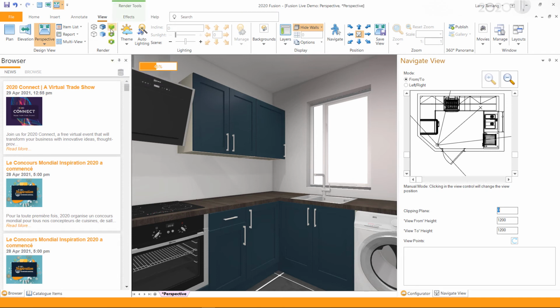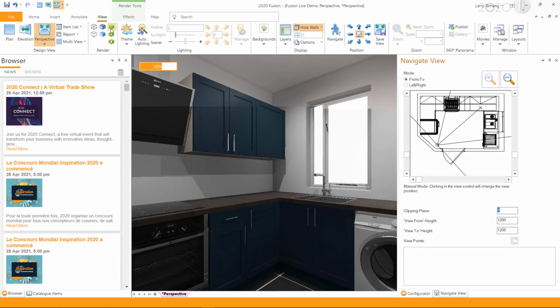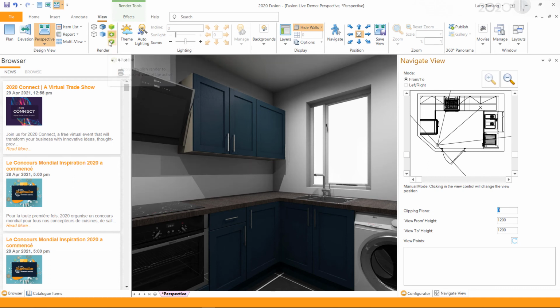If I go to the presentation, you can see here it is a much sharper image, but then again also extremely quick to render. Now I go to the presentation plus, which is the next level up. It has to go through a couple of additional passes to render the image, which gives you a slightly better picture. And again, the render is quick. Next level up, we have the publish render, which is the highest render. This render goes through several additional passes to give the image a good render, and it smooths out the shadows and reflection in the design, and thereby giving it a more realistic look.